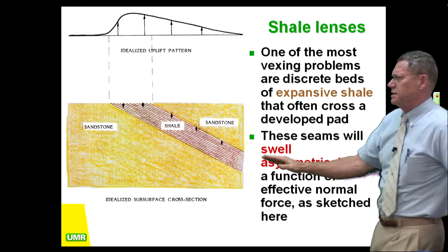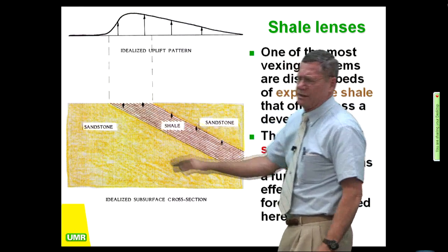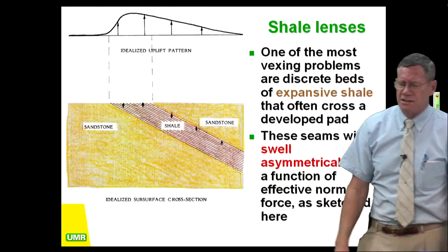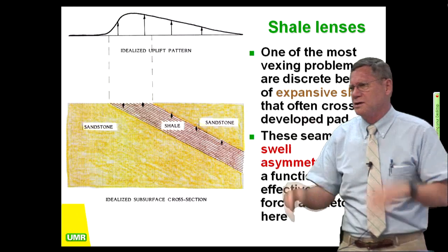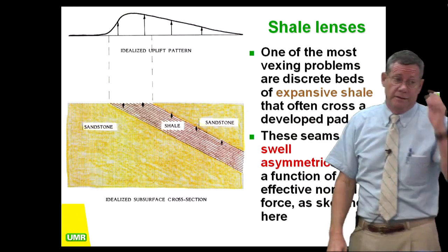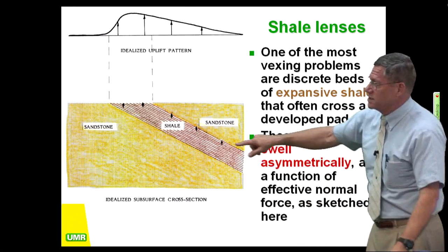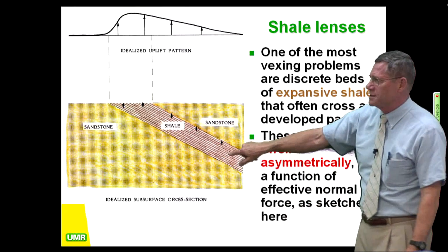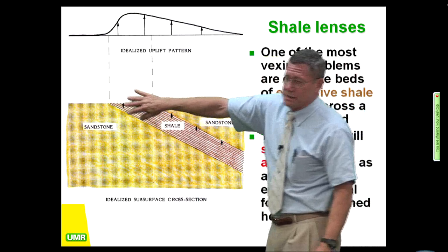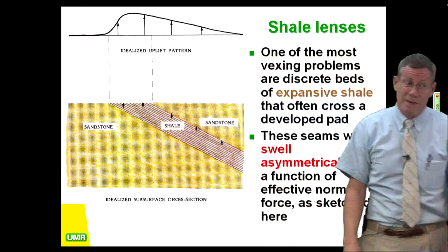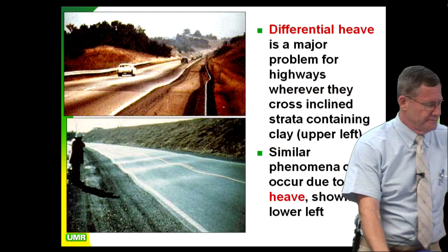So here's where you really got to have the engineering geologist out there with his eyes screwed on saying, hey, we got little shale stringers in here, 3 inches thick. The soil engineer's going, 3 inches, so what? We'll be putting piers to it, no big deal. Guess again. Can be a real big deal. If you got any smectite clays in here, you're hosed. You have to over-excavate down about 6 feet and backfill this with something else. 6 feet's a minimum, or it won't work.